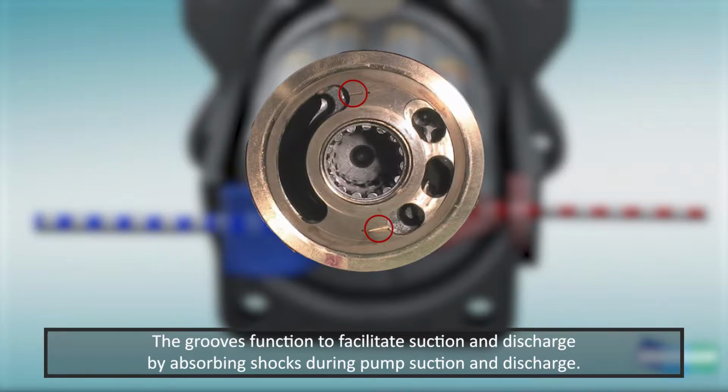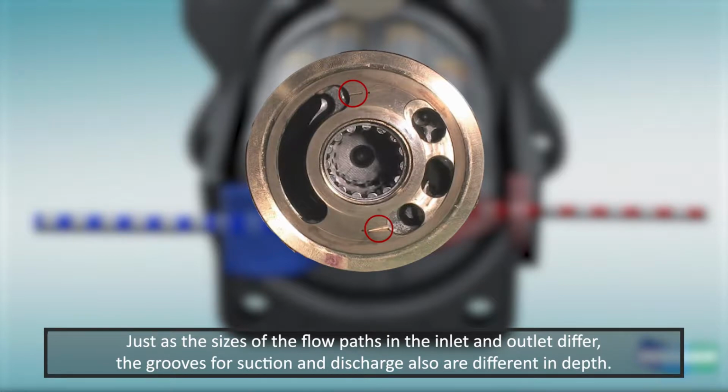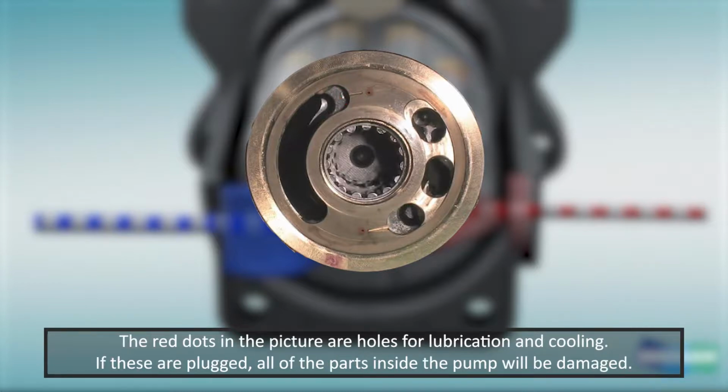The grooves function to facilitate suction and discharge by absorbing shocks during pump suction and discharge. Just as the sizes of the flow paths in the inlet and outlet differ, the grooves for suction and discharge also are different in depth. The red dots in the picture are holes for lubrication and cooling. If these are plugged, all of the parts inside the pump will be damaged.